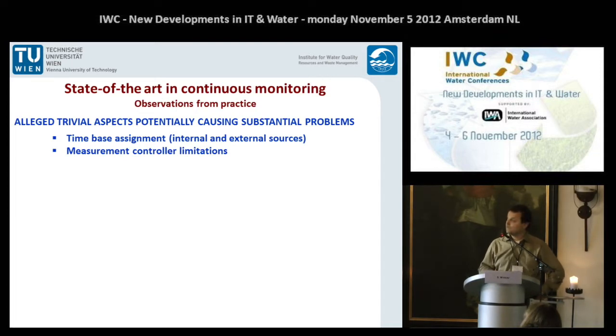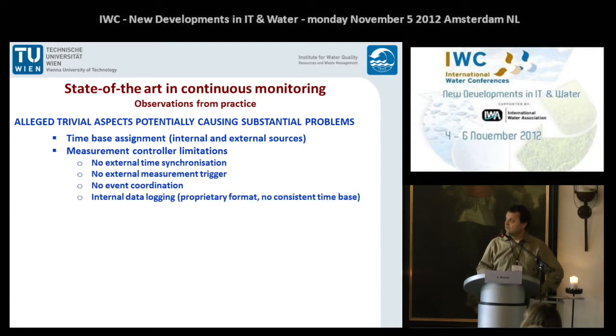It's not really documented. If you work with online measurements, you have the measurement controllers of different manufacturers, and most of them have quite some limitations. You have no chance for an external time synchronization. Usually you don't have a chance for an external trigger mode, or very rarely, so the instruments run on their time base of that controller, and every controller runs on his own time base.